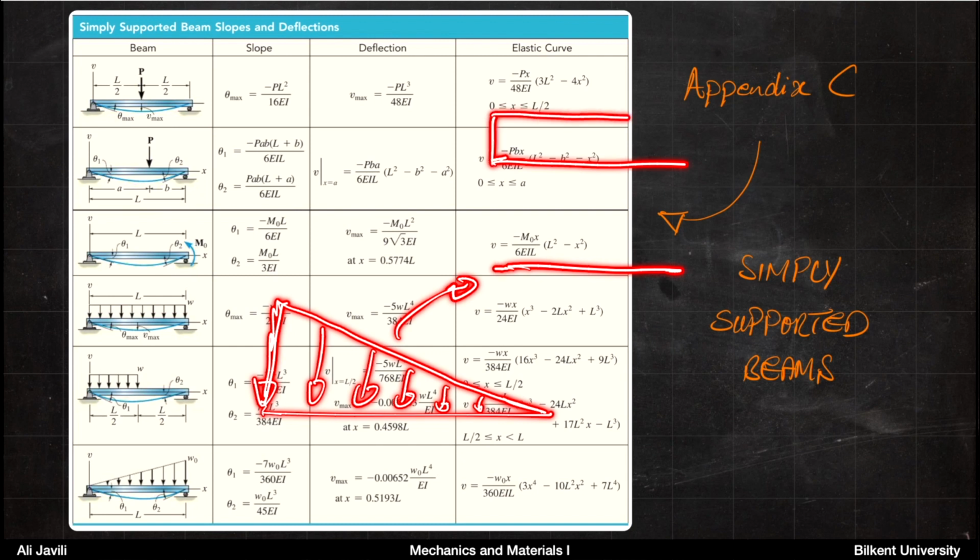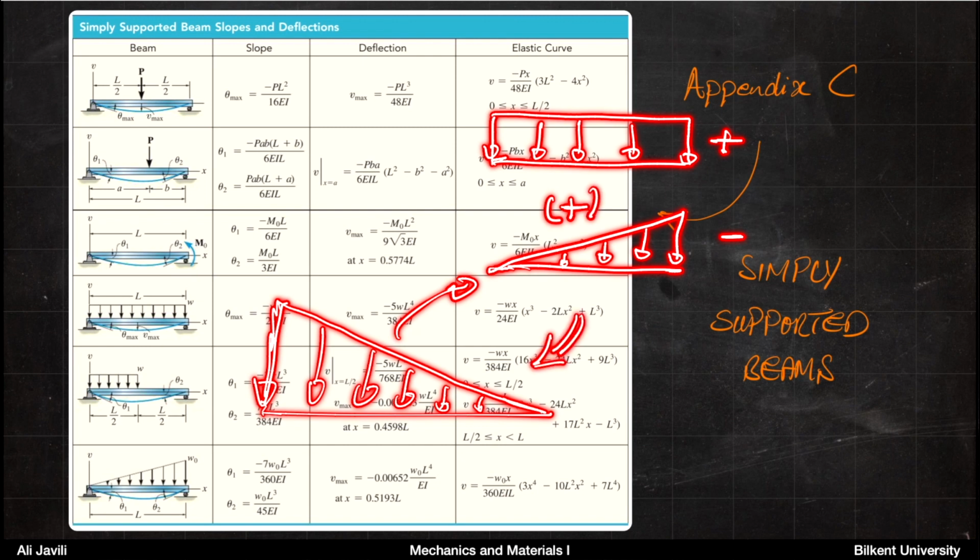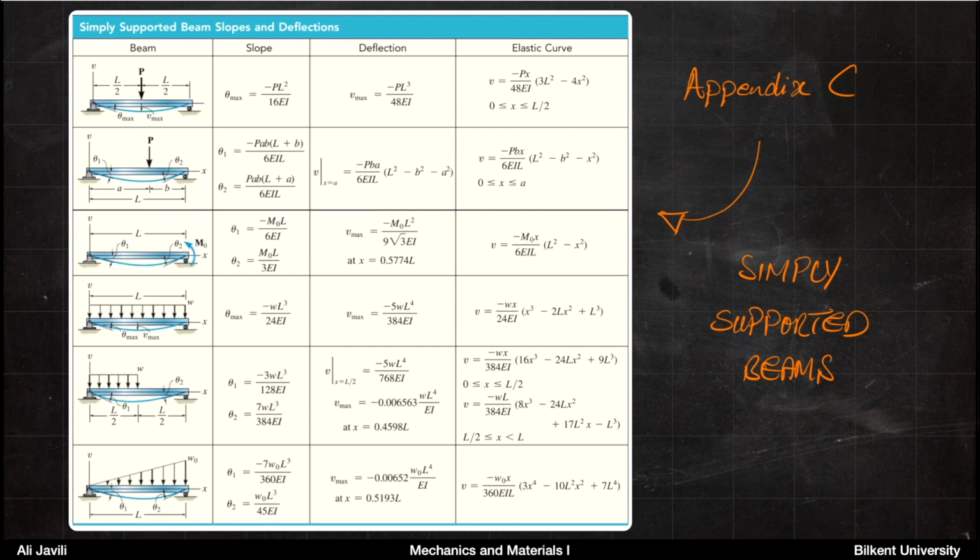by assuming that you have a system with a uniform load and then subtract a linearly increasing load from that. So if you take this with a minus sign, this with a plus sign, and you add the response of those two together, you can get into this case. Okay, so basically the idea is that you can use the method of superposition, obviously within the table itself, or combining different rows of the table.